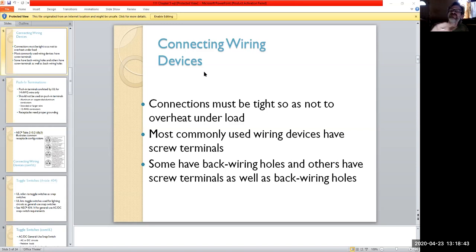Because otherwise what will happen is when you screw it down, it'll end up flaring it out. But if you screw with it, it'll actually pull it in and it makes a really tight connection. And always give stuff a good tug test. And that's with, if you're doing a junction box splice, where you've got wire connectors, give that stuff a good tug test. Don't be afraid of it.